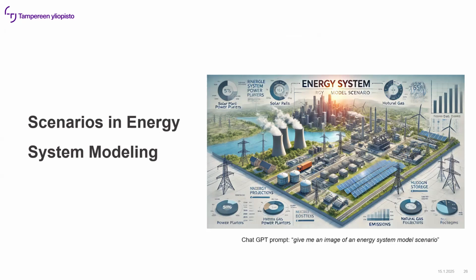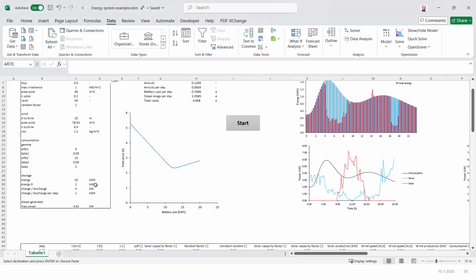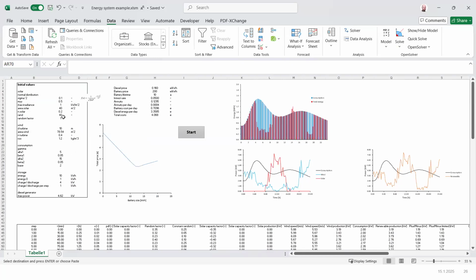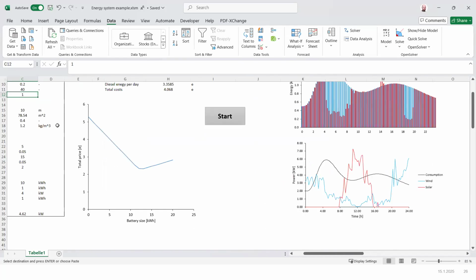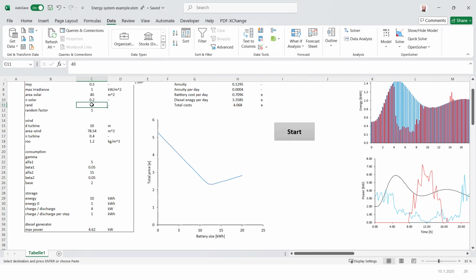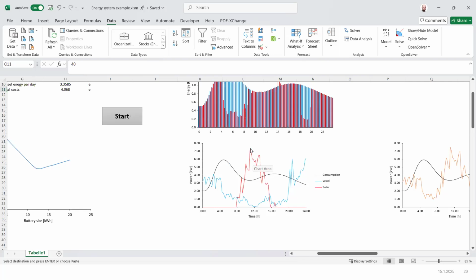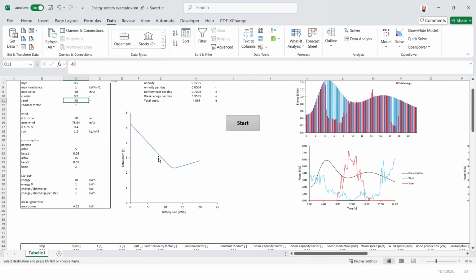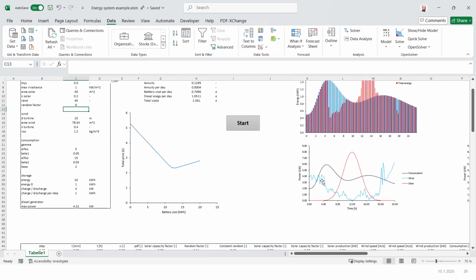So that's a really simplistic way of this Monte Carlo simulation. And again, the hardest part of that is determining the randomness factors. So what I mean by that is whenever I change this system, I have this random factor on, but what that does, it scales, so this rand 40 means that up to 40% I can take out of this normal distribution.